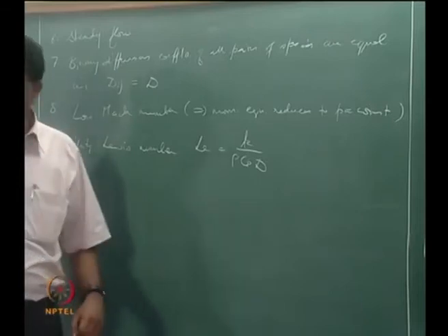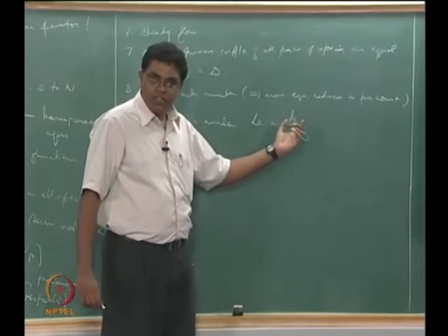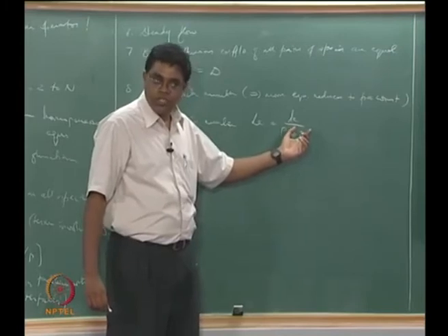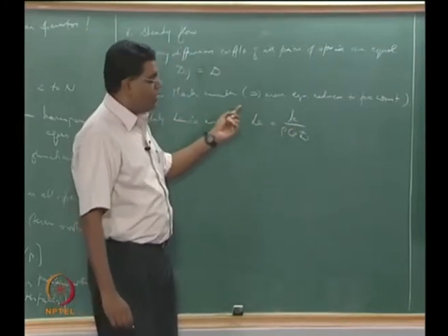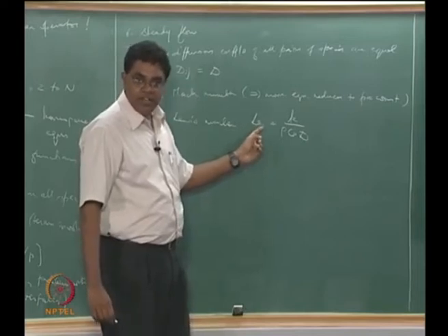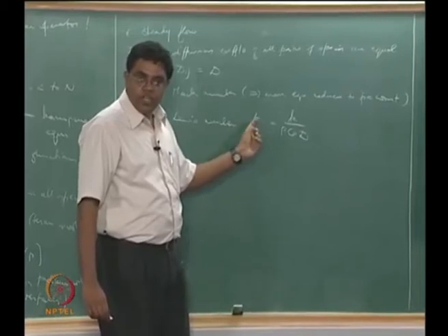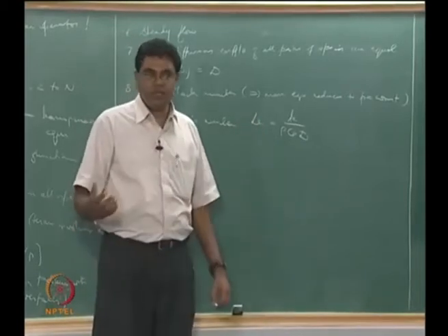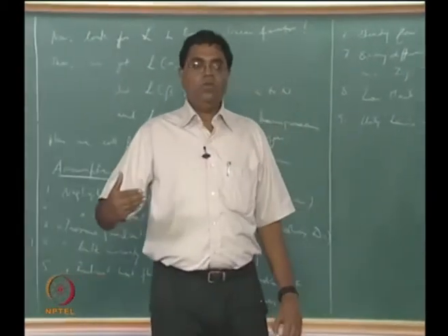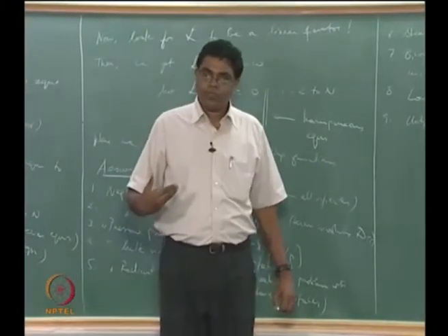But many times, as we have seen earlier, the Dij can be replaced by a Di, the multi-component diffusion coefficient rather than the binary diffusion coefficient, in which case we will have to recognize that Le should be written as Lei. That means it is different for different species. So you are looking at a Lewis number that is really species dependent, and many times people talk about a fuel Lewis number or an oxidizer Lewis number that are distinct from each other.